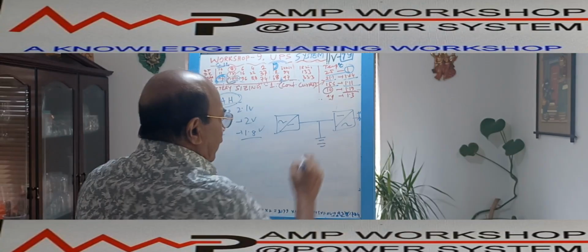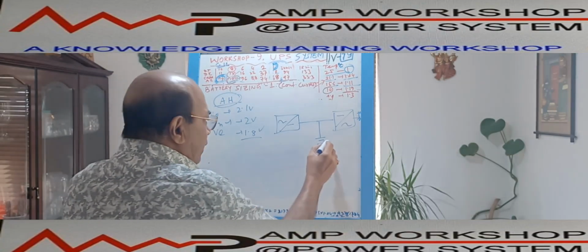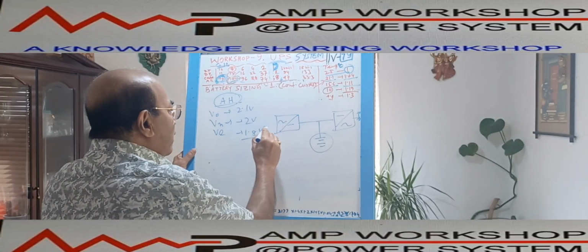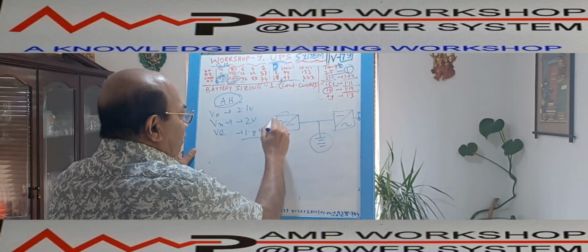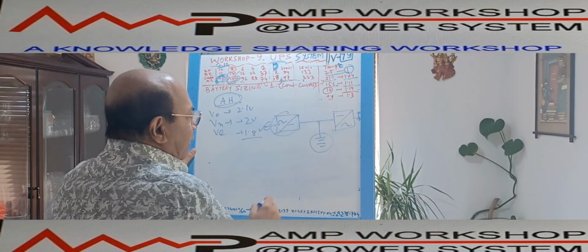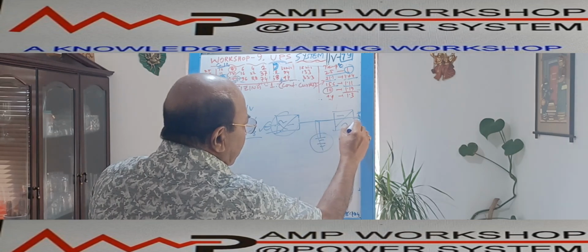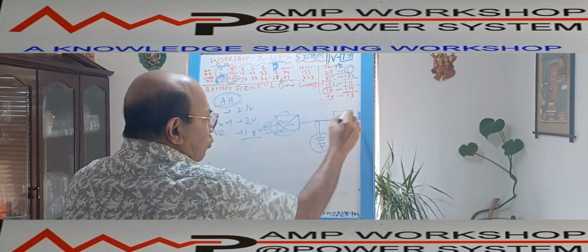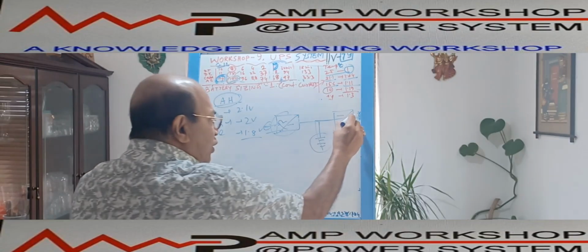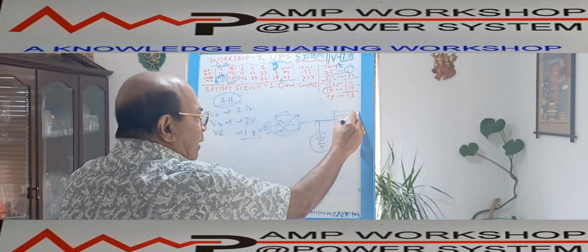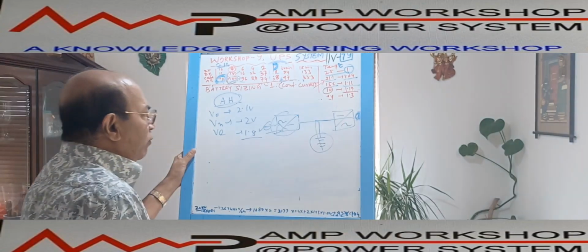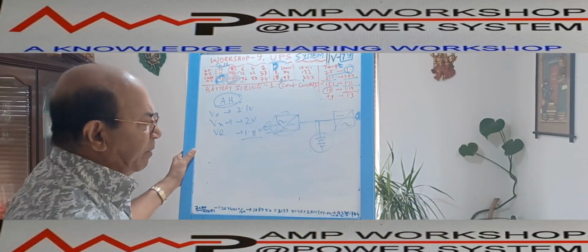Here the output is connected. So now when the battery comes into the picture, when the AC supply to the converter or the rectifier drops or fails, then there is no input power, so the battery will get discharged and deliver the power, and the output is to be maintained. So depending on the UPS output requirement, we have to calculate the battery sizing. That is the basic thing.